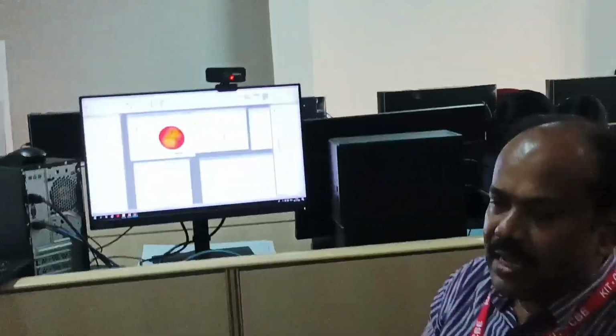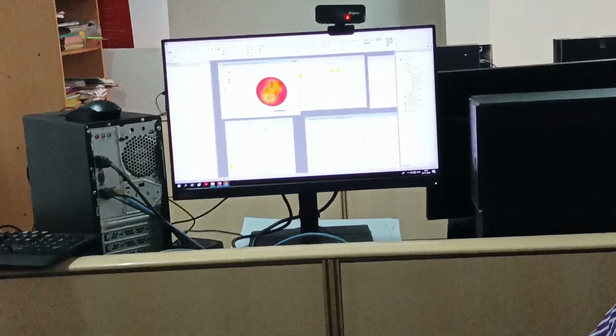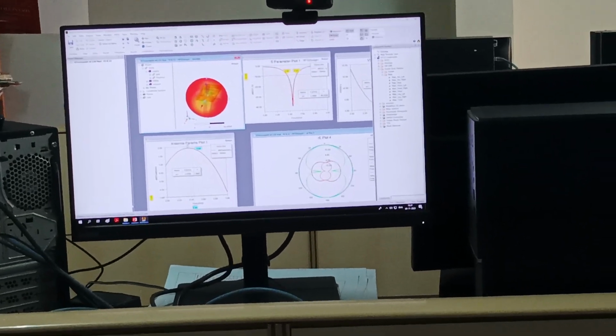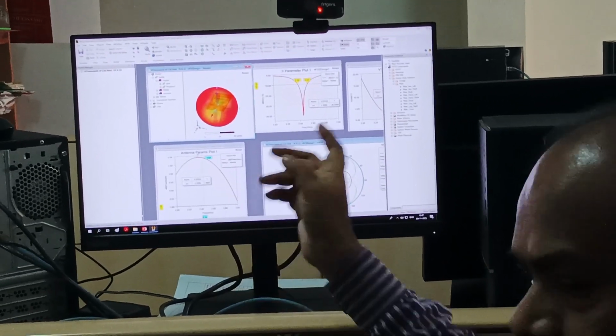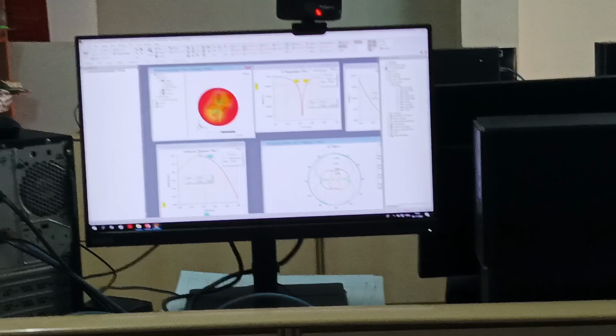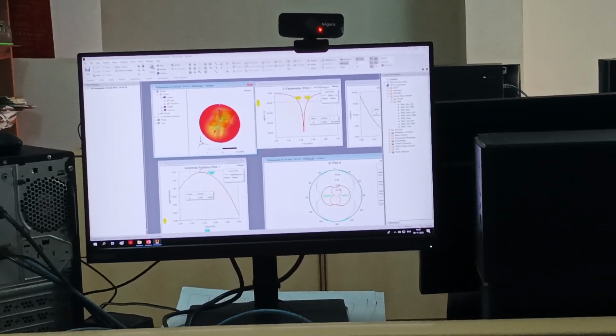The antenna looks like this. The type of feed that we have is a coaxial connector, and the positive terminal of this connector will be connected to this radiating patch, and the negative terminal of this connector will be connected to the ground plane. Now, the traditional antennas available use rigid substrates, for example FR4, Rogers, RT Duroid and so on. Those substrates may not be suitable for wearable application, and hence we use PDMS.